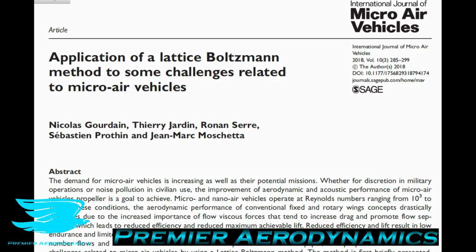For Lattice Boltzmann CFD, we use Lattice Boltzmann equations, and there's a bit of a misconception out there to some extent. The main way of explaining the Lattice Boltzmann method is that instead of looking at the macroscopic level, you look at the microscopic level. So you look at each particle. That's not strictly true though. You're not looking at each particle. What you're looking at is the flow from a particle point of view, but you're not looking at each particle. That's an important distinction to make.